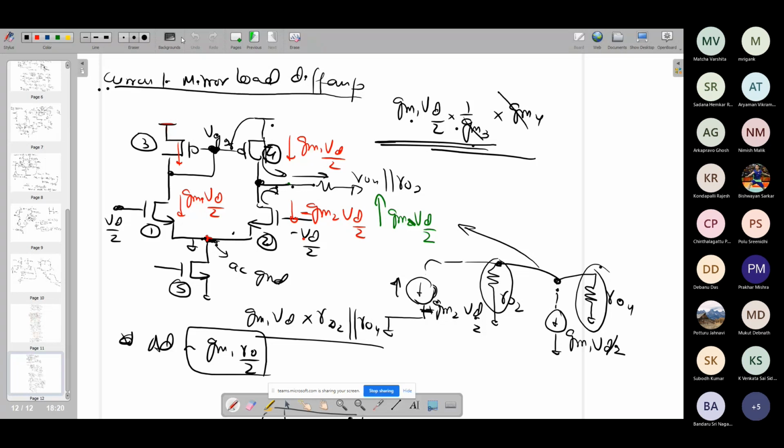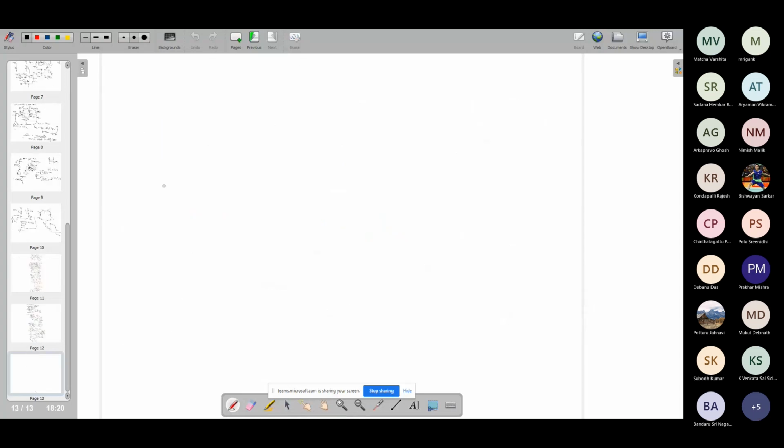Any questions? Sir, I have a doubt in experiment one. If I connect 0.9 volts to the M1 MOS, we did it for 891 millivolts, but if I do it for 0.9 volts, I'm getting a two-pole graph. The graph shows it as two poles. I don't know where the two poles are occurring in the circuit. First of all, make sure that whatever voltage you're applying, all the transistors are in saturation. So if you change the DC operating point,